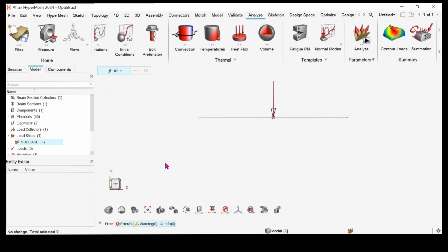So now select this contour. We are in HyperView now. Select this contour, displacement, mag, and click on apply here. So now you can see the deflection, maximum deflection, 1.2, 10 to the power of 0. That means 1.2 mm.